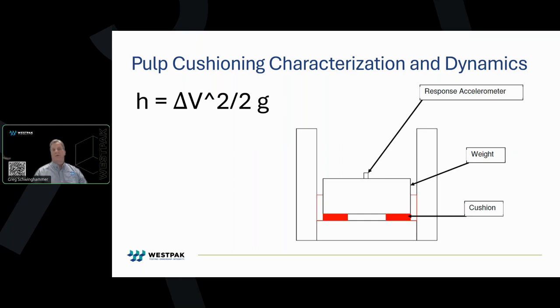Since pulp cushions are dynamic, pulp cushion dynamics are largely shape dependent. New or modified procedures are required in order to determine its impact and vibration performance properties. The procedure established for testing described here is a modification, like I said, of ASTM D4168, the procedure commonly referred to as the enclosed block test method.